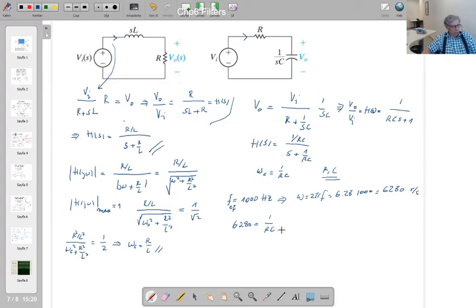How I am going to use that facility in engineering is easy, because I know the standard resistor values. There are many standard resistor values, but there aren't so many standard capacitor values available in the market. So if I choose one of the most available, cheapest capacitor values, C, let's say 10 microfarad, then we can calculate the resistor value.